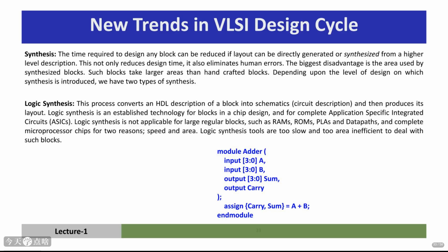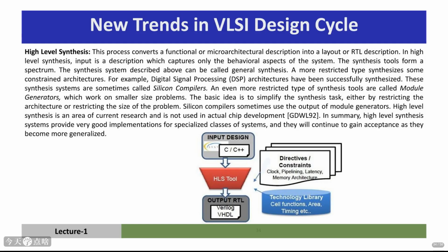The example here shows a simple Verilog module for an adder. Logic synthesis tools would take this description and generate the gate-level implementation. Taking automation further, we have high-level synthesis, or HLS. This aims to go from an even higher level description, capturing just the behavior, perhaps in C or C++, directly to a layout or RTL description. It's a much more ambitious goal.